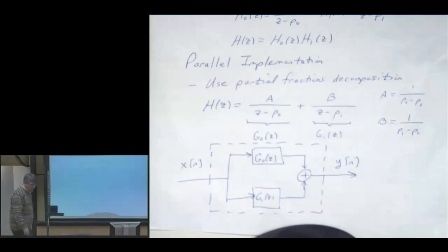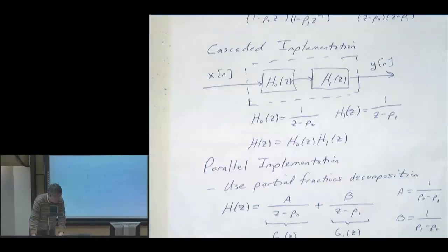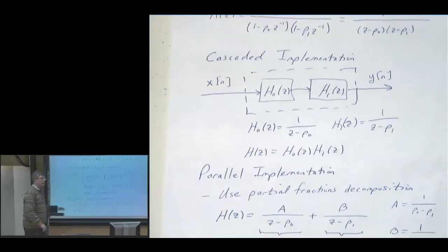The factored form has the advantage that essentially I'm filtering before I'm filtering, right? So I'm filtering by H0 before I filter by H1. It goes back to quality factors and things. So I can choose carefully the ordering of these sections so that I have a better outcome in terms of the implementation from input to output. I'm closer to the filter that I really want, but I have the ideal filter.